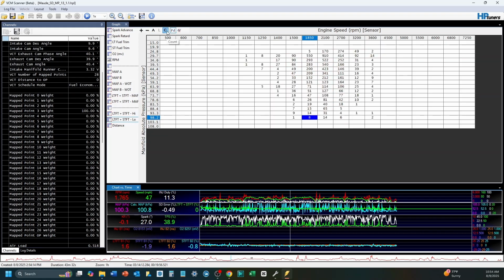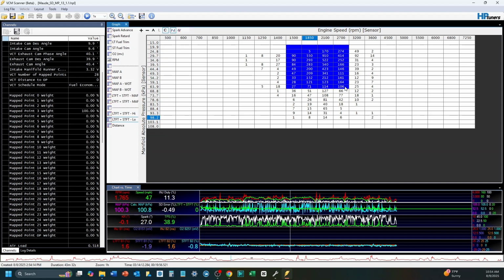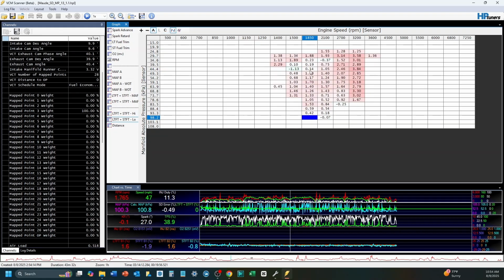This was a 43-minute log, pretty good, and you see we're hitting some pretty great data points. Obviously in here is my really accurate pocket. I would even say, in here is hyper accurate. I can take that to the bank. This is definitely just a little lean, right? And that's what I would expect to see given that we're stock, and this is what Ford gave us, right? It's no big deal. And this has gone through one iteration of tuning already. When I started, it was probably like 5%, 6% lean. But these counts are pretty good.